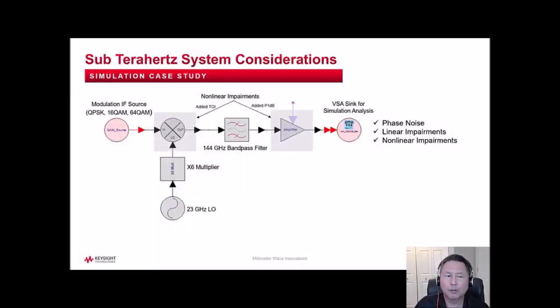When upconverting, removing undesired image products, LO feed-through, out-of-band spurious products, and emissions typically requires filters. Filters, as well as other components in the system, such as mixers and amplifiers, can introduce linear amplitude and phase error over these extreme bandwidths. So an adaptive equalizer can help to mitigate some of the linear amplitude and phase error, similar to what might be implemented in a baseband receiver.